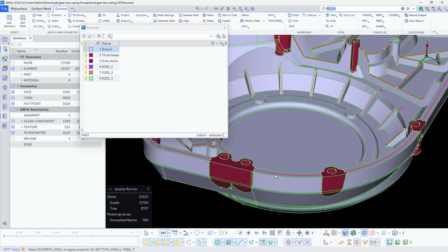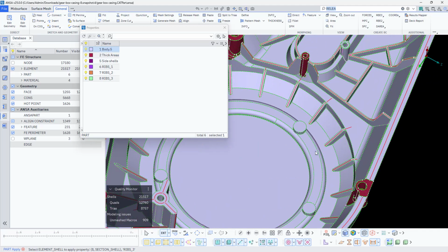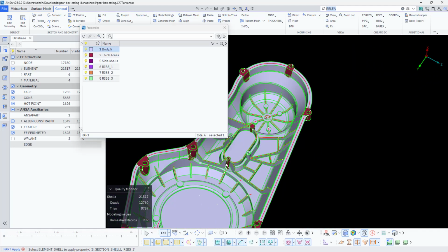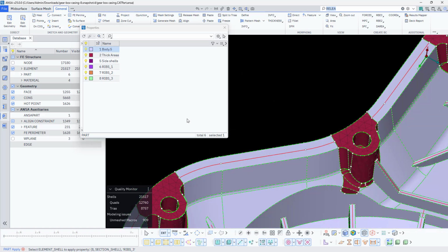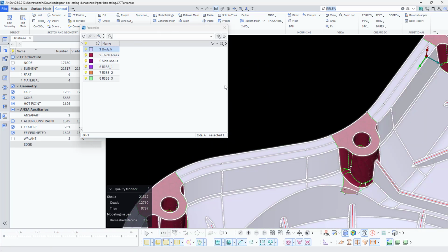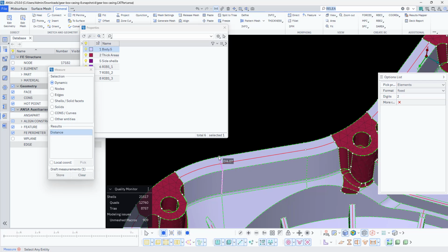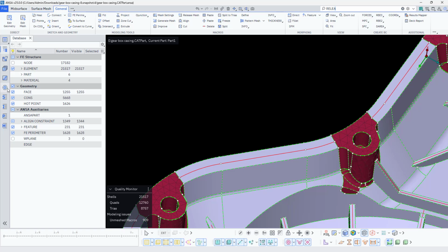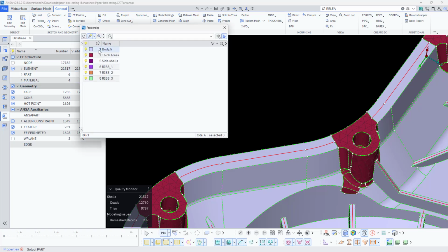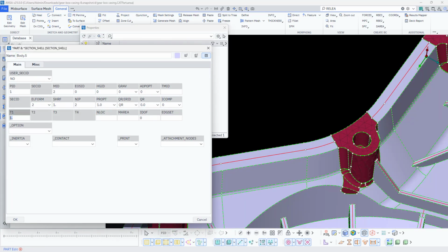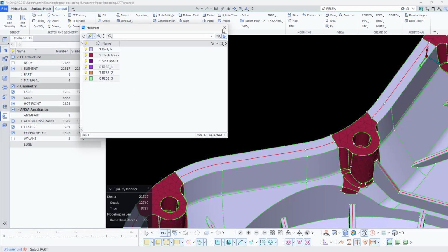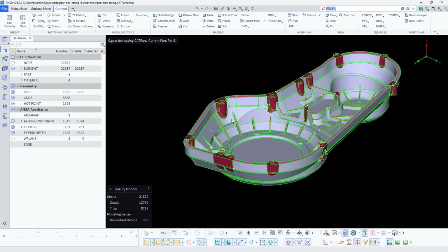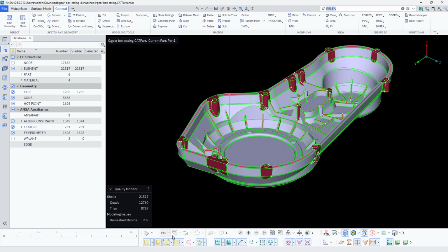So to see the thickness, what you can do is you can activate the shell to solid representation and check the thickness distribution. So here you can measure the thickness at a 6 mm. So we had seen it earlier as well, right? So I'll just switch to the property, and here it is T1. It's only one thickness, so I'll just change it to 6. Now if you do that, it will be changed, and if you want you can see the preview as well.